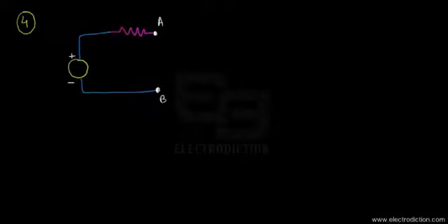We can connect the 3 ohms resistor somewhere right over here. The 3 ohms resistor would behave as our load resistor, since we are finding the necessary equivalent Thevenin voltage and resistance across its terminals.